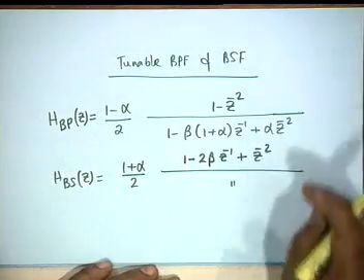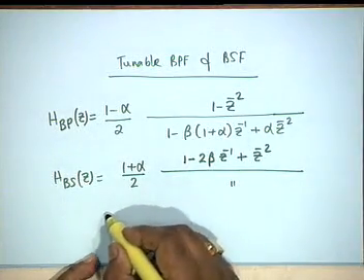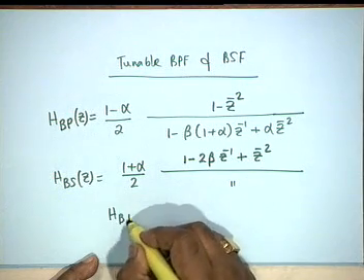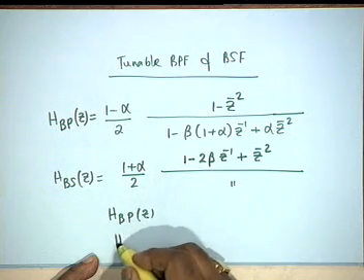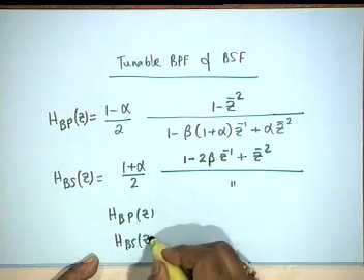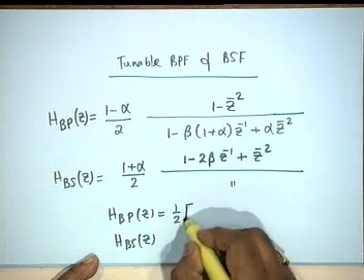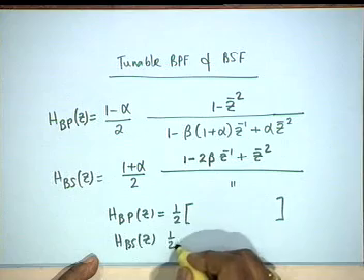If you recall our discussion on these two filters, alpha and beta independently control the bandwidth and the center frequency. Center frequency in case of band pass is the frequency of maximum, and in the case of band stop it is the frequency of rejection. Okay? So, both of them, H BP(z) and H BS(z), can also be written as the sum and difference of two all pass functions.